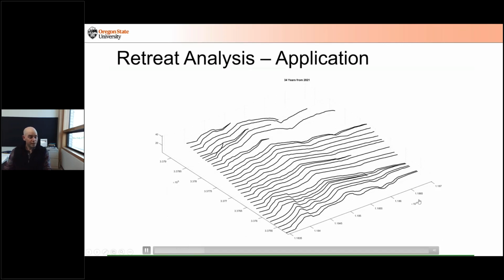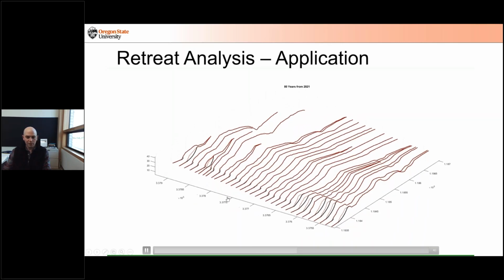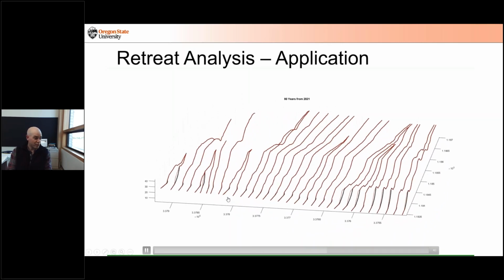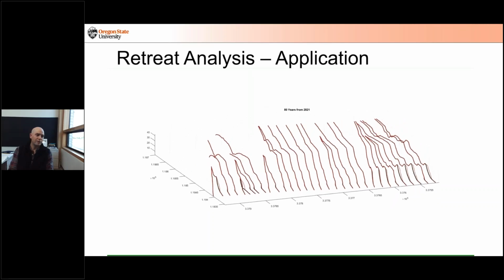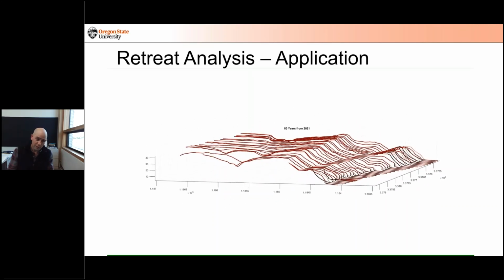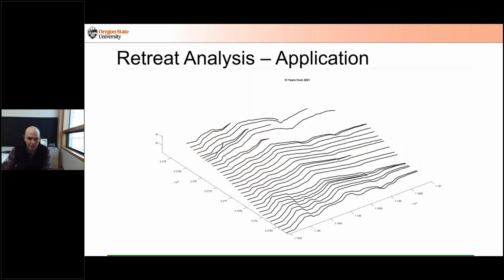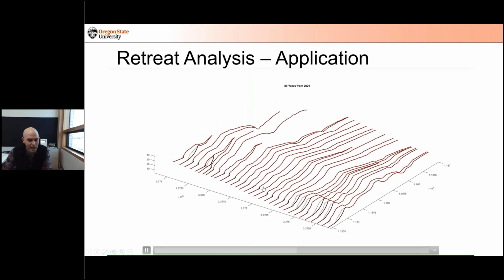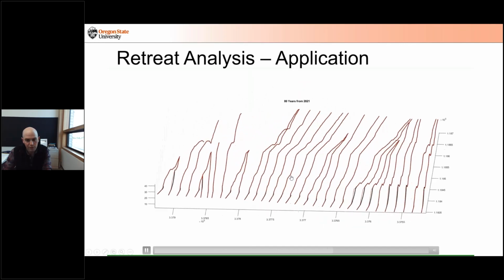We can apply this at a little bit of larger scale. This is for the site you saw before. You can see erosion occurring along the toe here and some full cliff collapses occurring as well. This was over an 80-year period projected for the given inputs, and the variability is so large that you can get very different answers with different inputs here, but it's a start. We can see that there's a concentration of failures in the south, larger failures, and that some of the areas don't really have large failures, where the road actually crosses here.